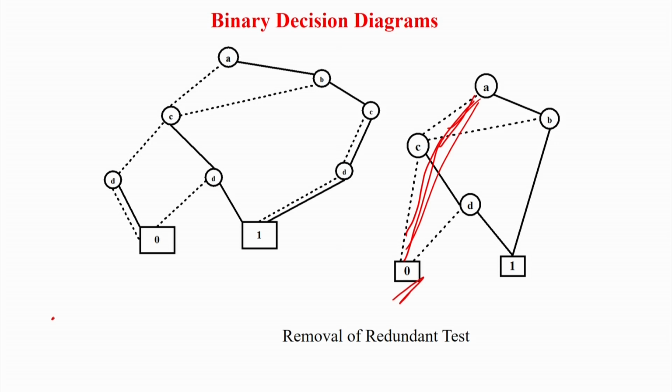So they are basically equivalent, but this is a very compressed version of the binary decision tree, and the compression happens because we are eliminating all the redundant nodes. First you eliminate all the leaf redundancies, then all the intermediate redundancies, then you find some nodes where both zero and one edges lead to the same child, and we eliminate those nodes and redirect the transitions accordingly. So you get a very compact structure. That is the beauty of binary decision diagrams.